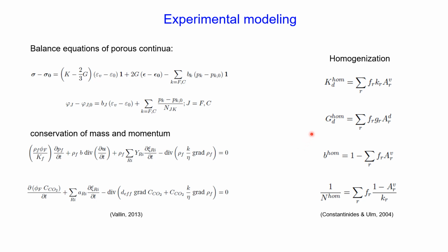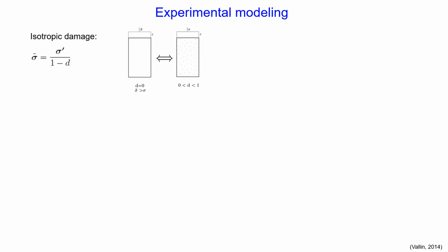All cement components have to be considered in the homogenization analysis in terms of their mechanical contribution to the overall stiffness. Anisotropic damage is considered in the numerical analysis. The damage stress is based on the decrease of the effective area due to the appearance of microcavities.